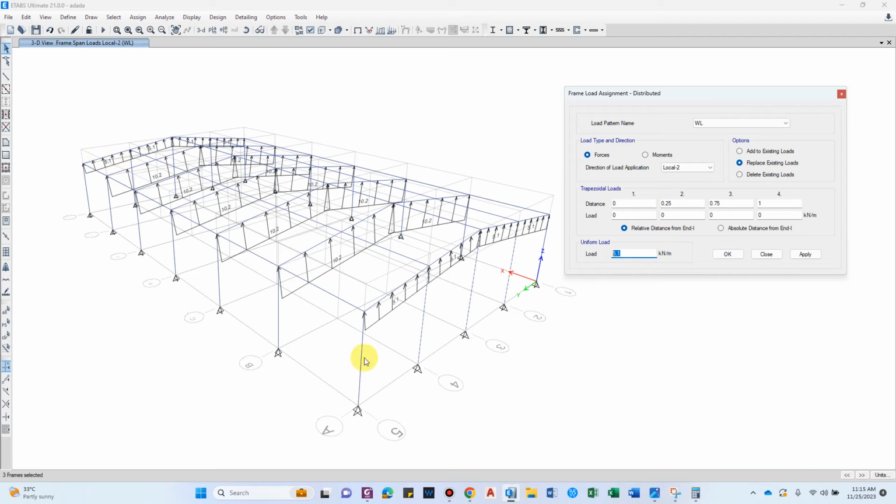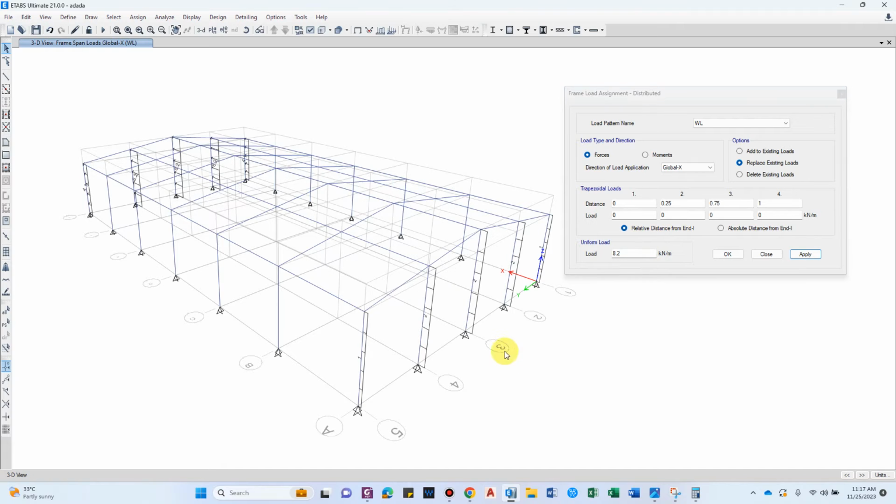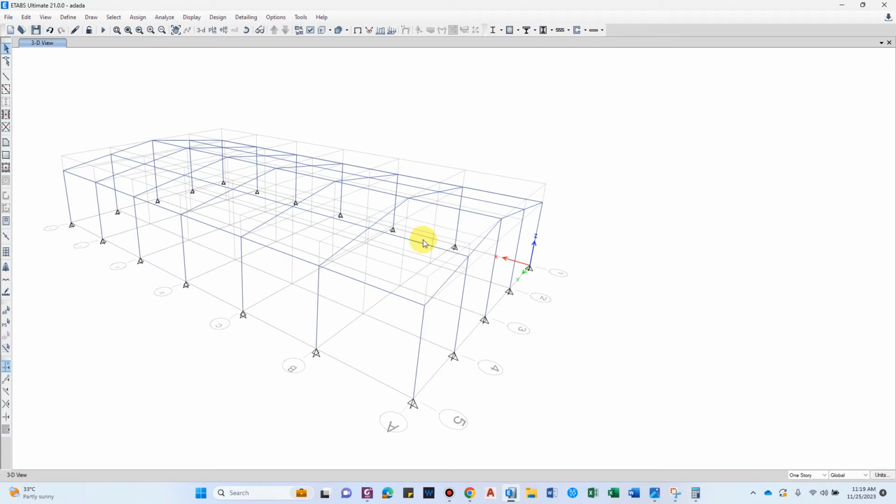Regarding these conditions, that is equal load on this face and equal load on that face being symmetrical in nature, we'll just consider this load only. Now we have this loading arrangement. And the other thing we have to consider, as I said, these will have a simple pin joint connection.